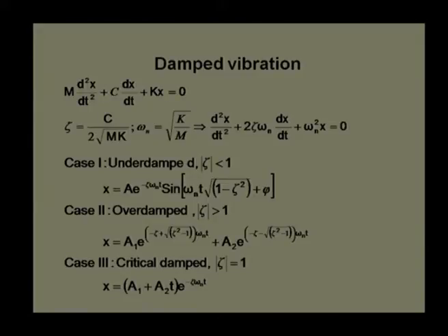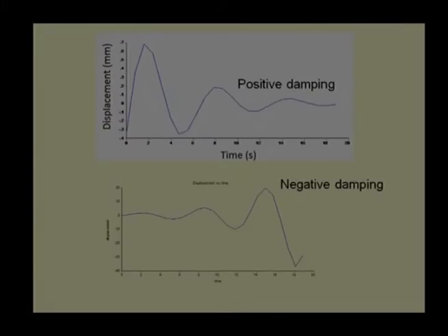We do not consider zeta as negative here, we do not consider negative damping at all, but there is a possibility of negative damping, even though physics does not permit us to say what negative damping is, how heat generation, how energy generation will happen without any input, but mathematically we can interpret it and we can show why friction instability occurs.